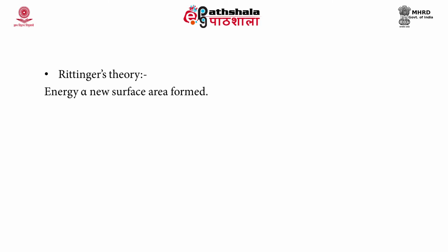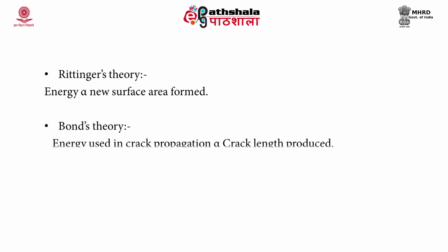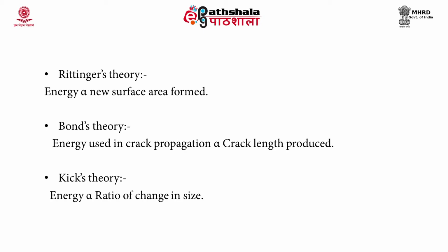operations. To summarize these laws, Rittinger's theory says energy is proportional to new surface area formed. Bond's theory states that energy used in crack propagation is always proportional to crack length produced, and third, Kick's theory says energy is proportional to the ratio of change in size.